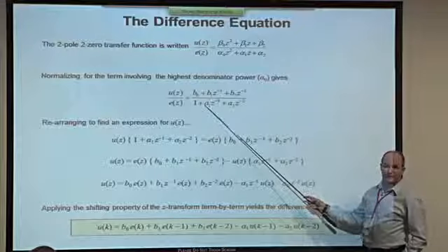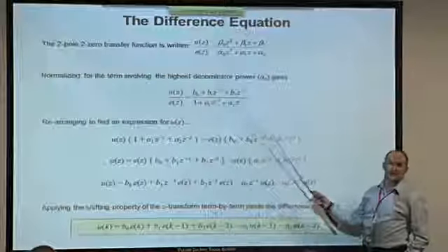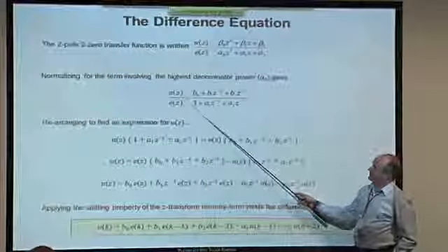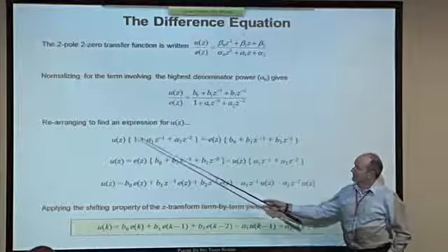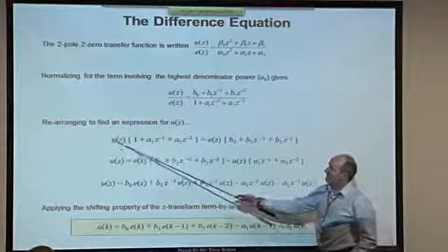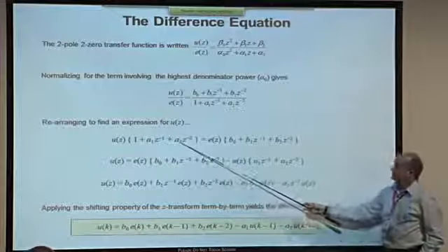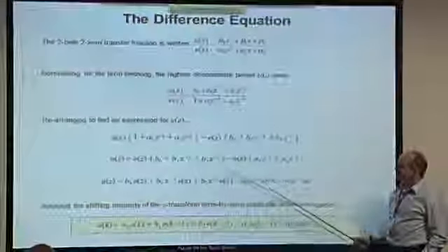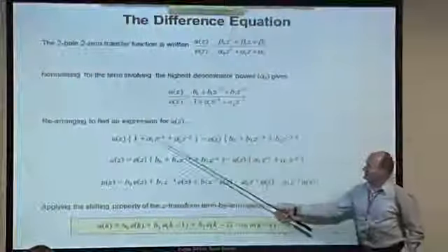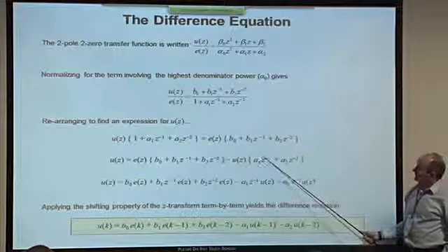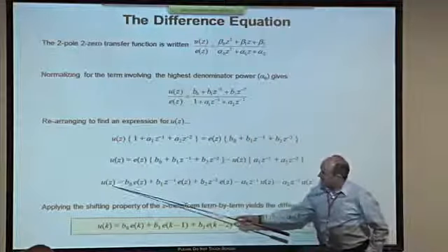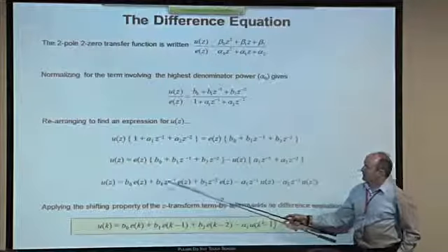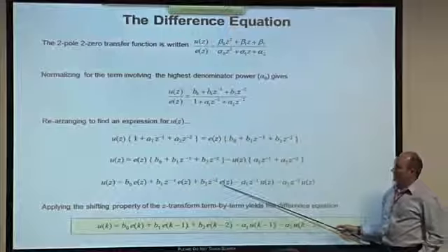And that's the form that DSP and software engineers like to see it, because, well, we can multiply through by the denominators on both sides, and now we're in a position to isolate this term on the left by subtracting these two from both sides. So we have U(z) equals E(z) times this polynomial minus U(z) times these two terms from the other side. And now what we can do is to just multiply these out. So what we have is b0 times E(z) plus b1 times z to the minus 1 times E(z), and so on.